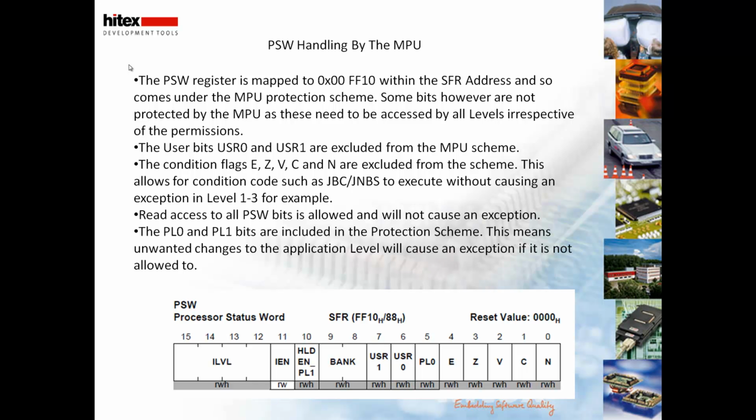First, of course, changing the bits from one particular state to another automatically enables the memory protection unit for that particular range, as soon as the bits have been written. So for example, if we have the program status word with both bits being 0, and PL0 is initially set to a 1, then as soon as we've written a 1 into there, the code that's currently performing this task has its level change from level 0 through to level 1.